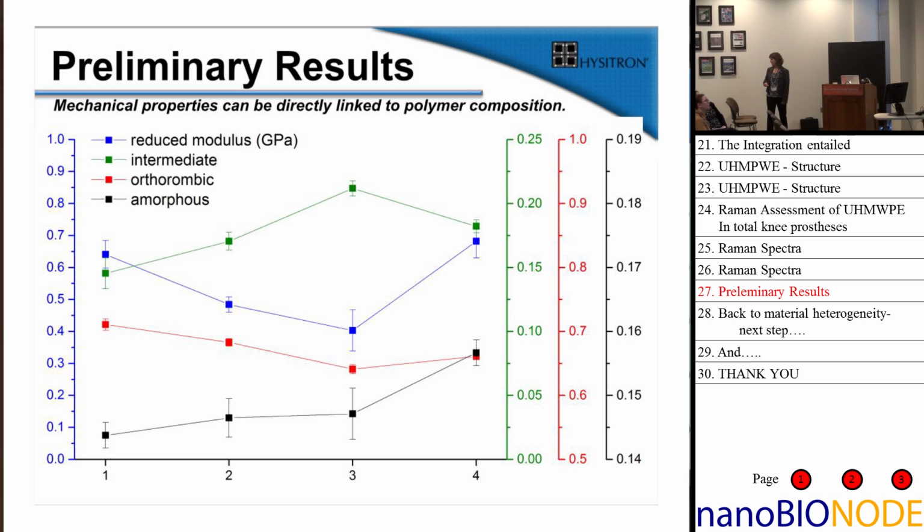When I looked at these slides that Yaroslav sent me last week, I thought, I have no idea what the difference is between these 4 materials until I started looking at this. I think the take-home message can really be found in the orthorhombic, or the red plot, where we're decreasing in crystallinity and we see a decrease in the reduced modulus. That's really nice, because it shows promise that we can start collecting in this one system in situ information about the chemistry and the properties of the same material at the same time, putting the material on the nanoindenter stage without moving it.